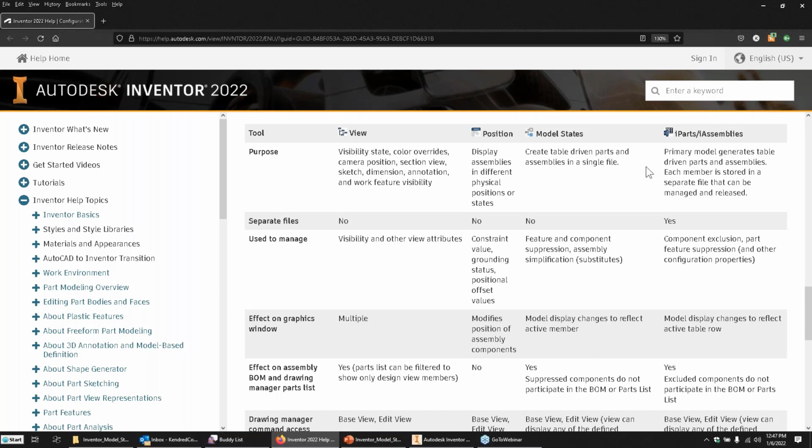That's the other thing when you're working with Vault Workgroup or Vault Pro on a model state, you're releasing that IPT. You're not releasing that individual model state. You assume it's going to be released with it, but Vault Basic and Workgroup and Pro in the grand scheme do not access that individual model state of the piece part. You have to incorporate the use of items, which in that case, you're releasing the item associated with the file.